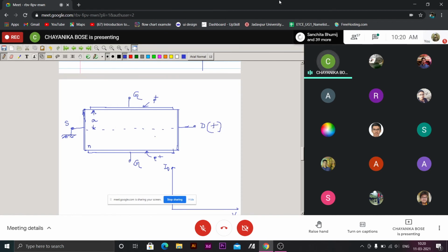So the channel conductivity will vary, and thus the current flowing from source to drain will also depend on the reverse bias applied at the gate. This transverse field from gate to channel controls the effective cross section of the channel available for current flow.